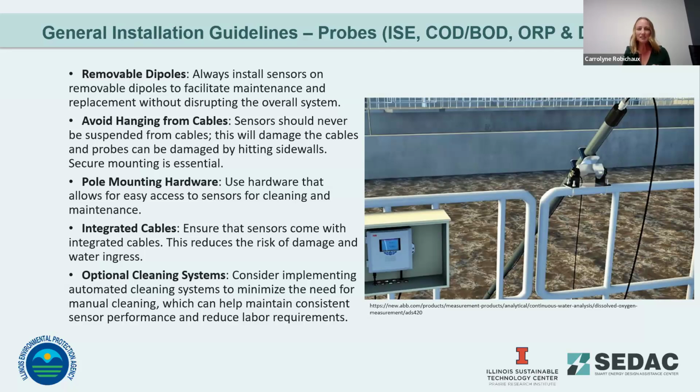Some plants are doing this over water. I don't know why you would want to add more water to the process. It can be useful in other parts of the facility, say like at influent or even effluent, where you might have non-potable water to be able to recirculate right there. But for aeration, it's mostly recommended that you're going to use just an air compressor. So the difference there is going to be air compressor, less manual labor for cleaning, or having to remove it from the process more often for cleaning. So kind of OpEx versus CapEx there. I think I covered everything on that slide.